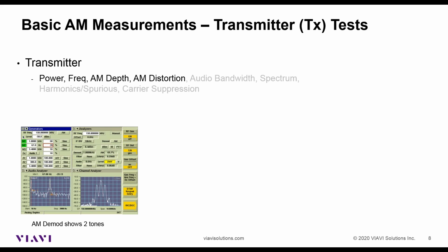Now, if you go to the analyzer on the right-hand side, in the demod section, you see the AM is measured just below 70%. So again, remember that the combined AM depth, we have a peak of 70%, which is what we measure on the AM meter. And that's quite important because just like we've talked about with FM radios and good tuning of digital radios, which generally tune using CW and FM, noise is an important factor, because with the FM deviation meter, if you add noise, or if your instrument, your test set adds noise, that will add to the FM deviation measurement.